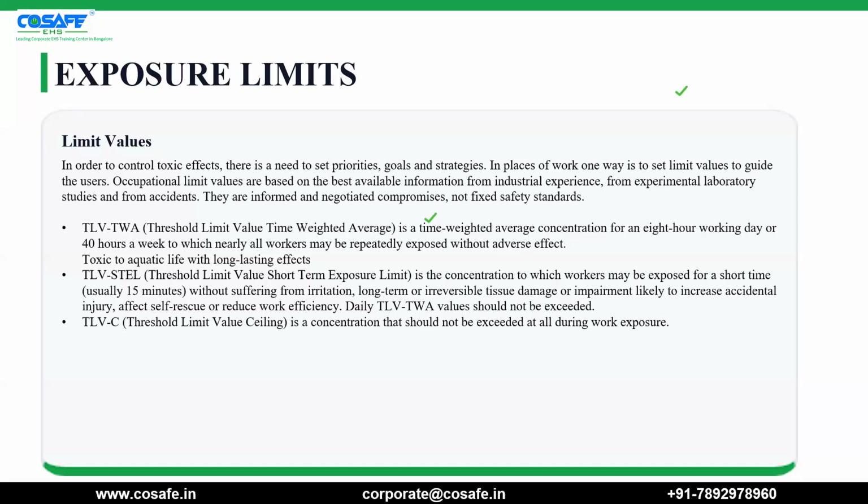There are three types of limit values. One is TWA, time weighted average, which states a person can be exposed to a certain hazard for an average time in an 8-hour working shift. Then the short-term exposure limit, which states that a person can be exposed to a certain hazard not more than 15 minutes without adverse effects on his health. Then TLV-C, threshold limit value ceiling, a value where a person cannot be exposed to a hazard under any circumstances.